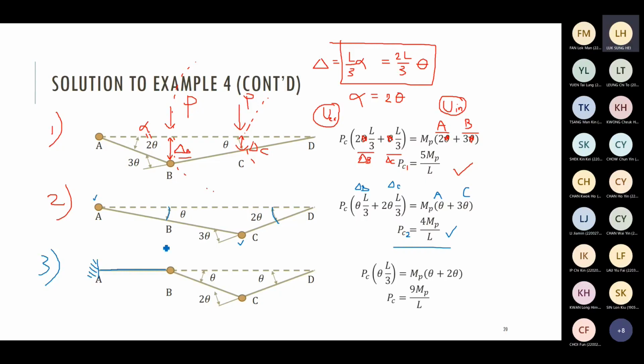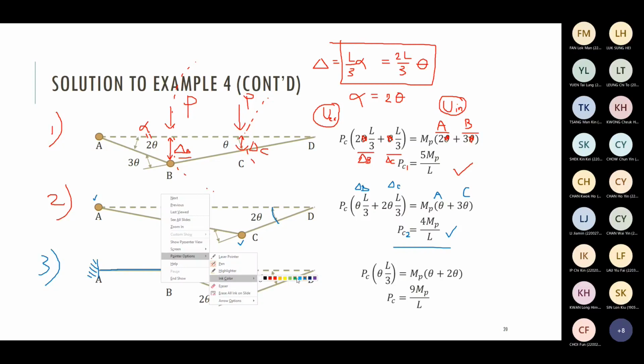So it becomes a horizontal line between A and B. The deformation only occurred between BC and CD. When you take a look at this deformation shape, it seems that it's not realistic, right? So that's why at the beginning, I think that this is not quite possible. But in theory, you may have hinges at point B and point C. So we will do the analysis for this not very critical scenario.